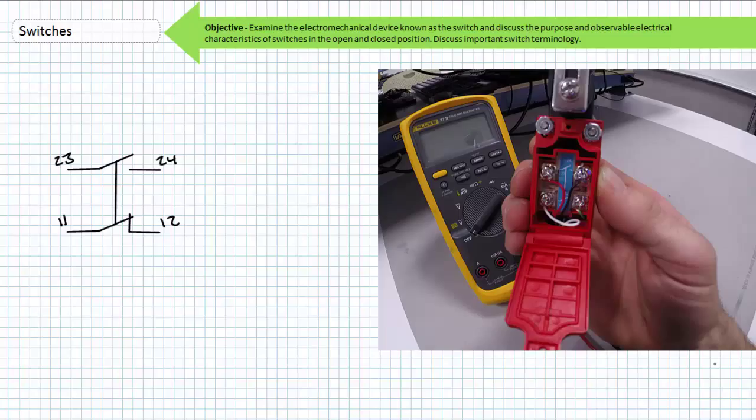Two, you'll notice it's using subtly different schematics and terminal numbering. Don't worry about the rationale behind the terminal numbering for now. I'll explain this later. This is also an integrated package of two switches. The lower switch is between terminals 1-1 and 1-2. The upper switch is between terminals 2-3 and 2-4. I want you to take a guess at what the schematic means. This limit switch is using IEC schematics.